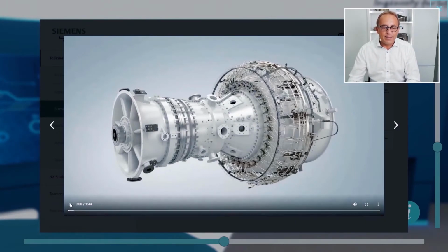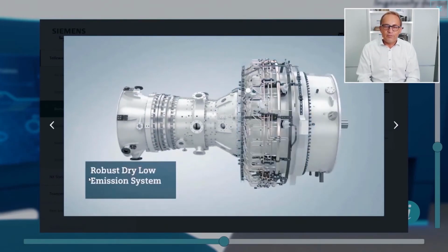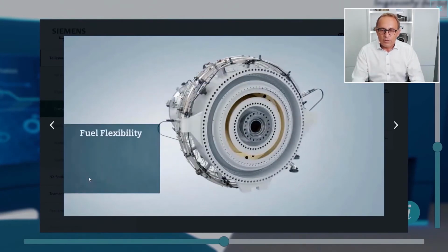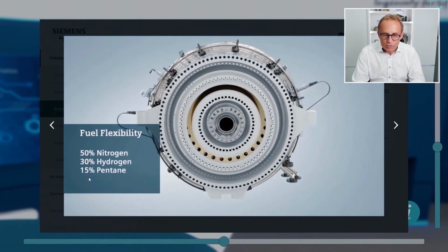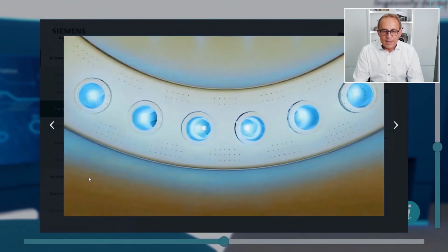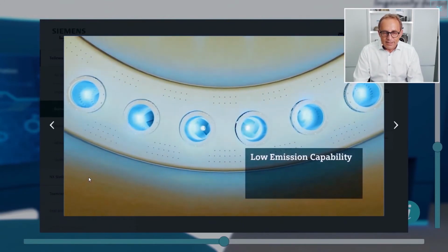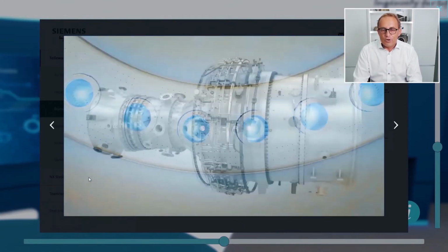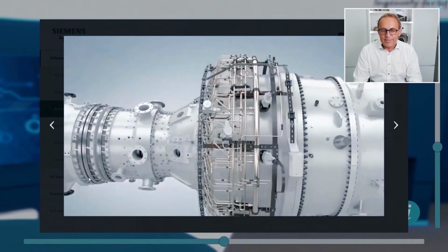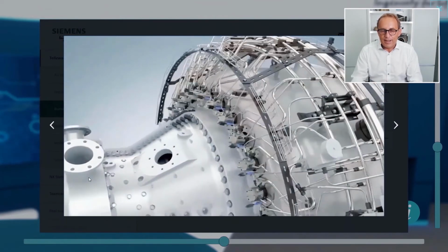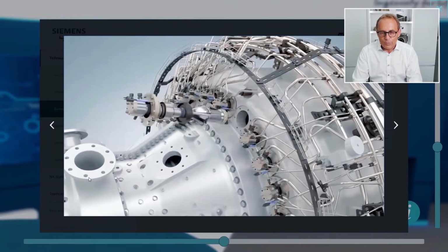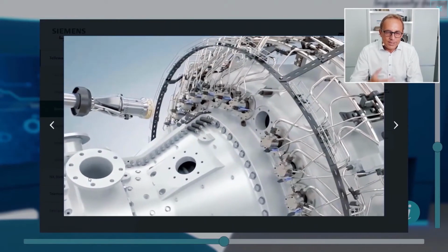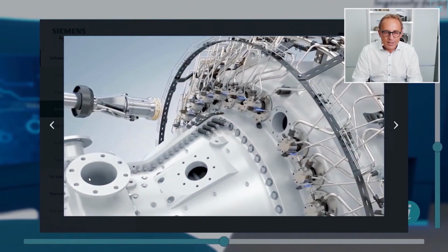And this is such a gas turbine. They are really impressive and big, and we use 30 of these burners in this gas turbine, and they thought about printing these parts. In former times, they were produced by 13 different single parts, where there's much effort for milling and drilling, for bending pipes and so on.